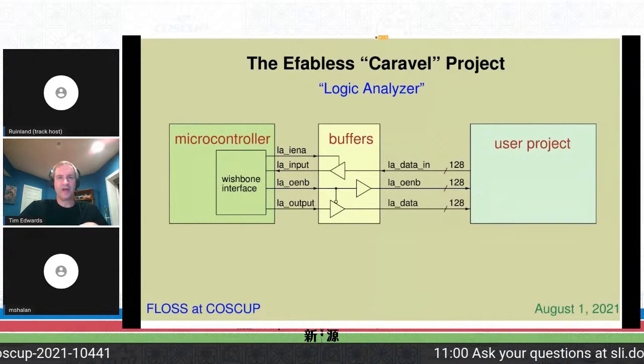Its main limitation as a logic analyzer is the onboard SRAM, because while it can sample data at a rate of maybe 30 megahertz or so, it won't be able to get the information off-chip at that rate, so it would have to be buffered in memory, and that limits the sample length that can be captured.